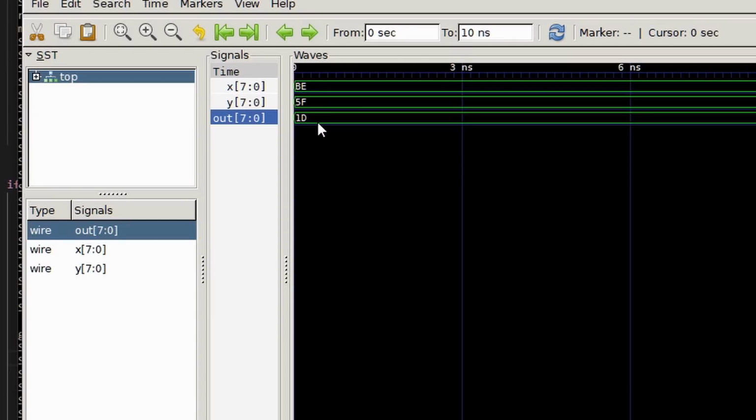Effectively, when you're asking Yosys to do covers, it will try to get the simplest result, but in some cases it's just going to be random. It's just going to be, well, you asked for this, and this satisfies those conditions. In general, when you're dealing with clocked logic, Yosys will try to find the lowest number of clock transitions that lead to your conditions for coverage. So that's pretty much that.